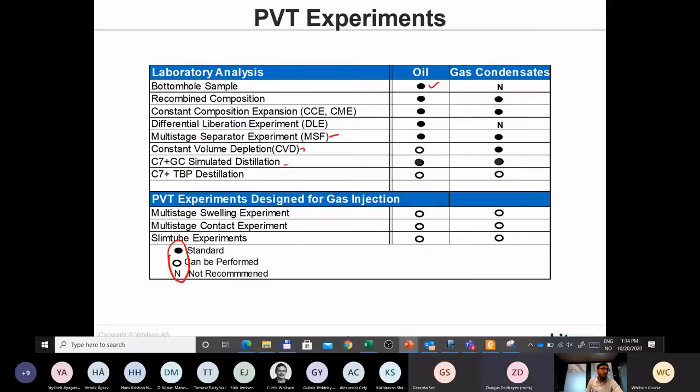Yeah, sorry, I just wanted to ask you one specific question. For example, for a gas condensate field, if we need the composition at a particular date in the future, and we use, for example, PVTI, which is the best experiment for that prediction, for example the composition at a particular date inside the well, if we need something related to some restriction in the bottom hole?